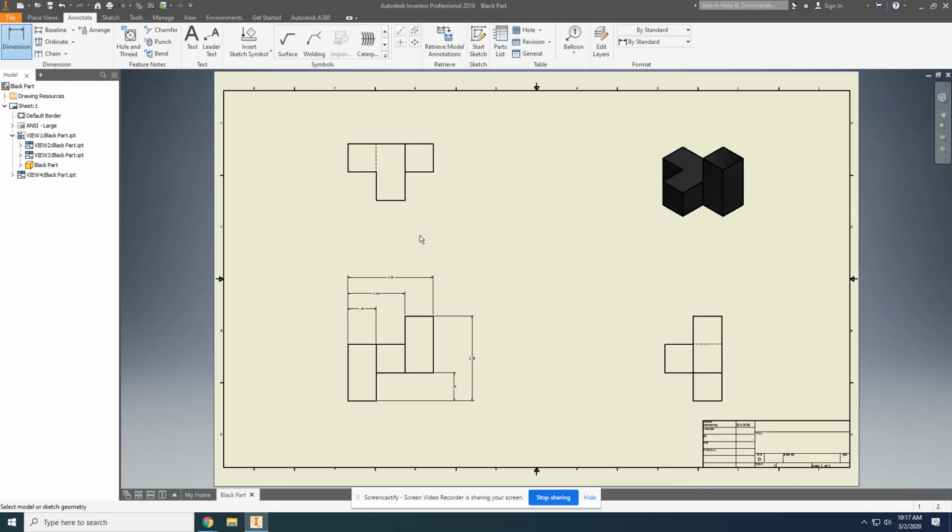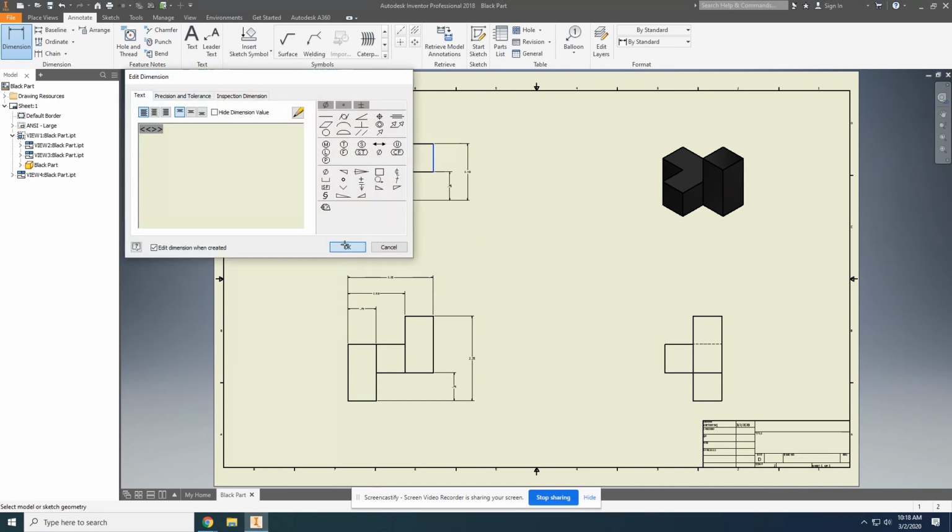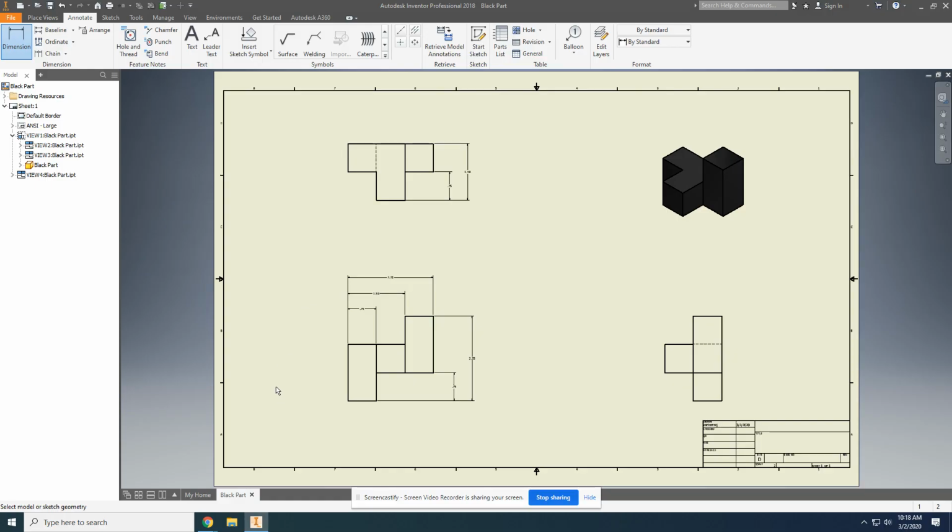The next thing I'm going to do is add some depth dimensions to this. So we're going to go from here to here. And then I'm going to do an overall depth from here to here. Now, there is one issue that we need to address, because you can't be guaranteed that this dimension is the same as this one. And that's something that we learned back in 3.4 during our application of dimensioning rules.